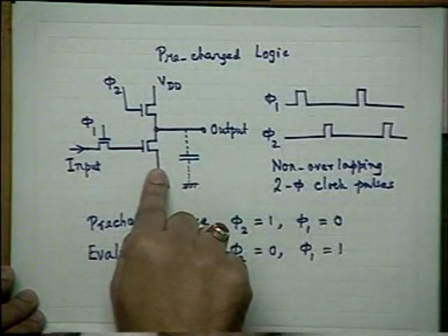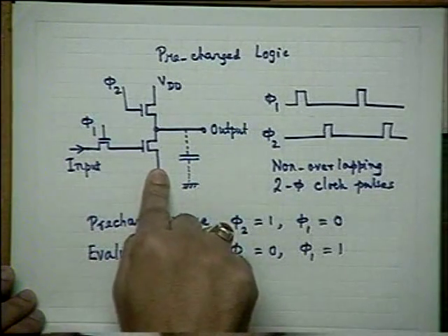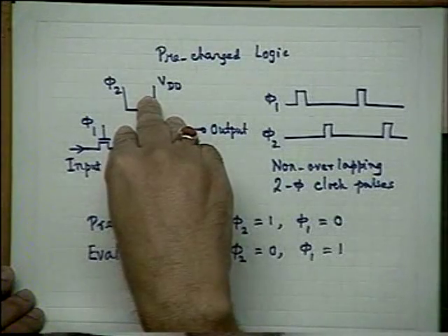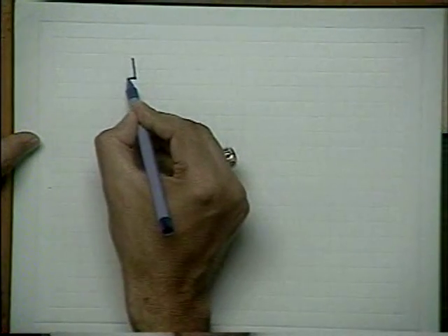In synchronous logic, the problem is that the speed of operation has to be limited. You have to supply clock everywhere. The speed of operation will be limited, packing density will be limited. Those are limitations, but otherwise synchronous logic is very good. And for those applications, this kind of inverter, rather than the ordinary inverter, is preferable. The same concept can now be used for realizing any logic gate. Let us see, for example, a NOR gate.